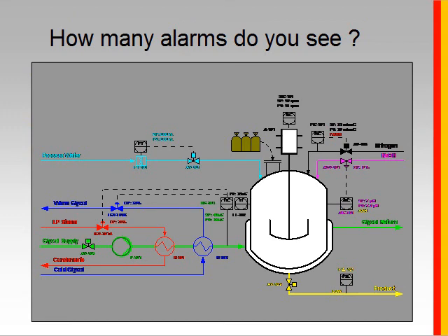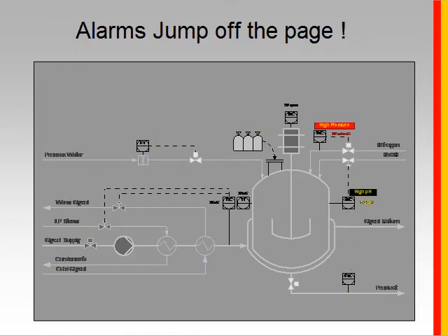And now I'm showing a screen. Hopefully it's reacting dynamically, and the question I would ask is, if you look at this screen, the typical operator display, how many alarms do you see? It's difficult to tell. Certainly for me it's difficult to tell. Let's compare this design, which is very representative of the way things are done, to a design that much more reflects the practices and premises related to the standard. Here you can see there's clearly 2 alarms. And what you notice in this case is that the alarms really jump off the screen.